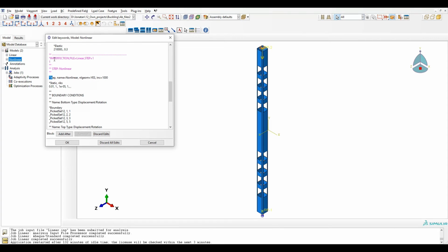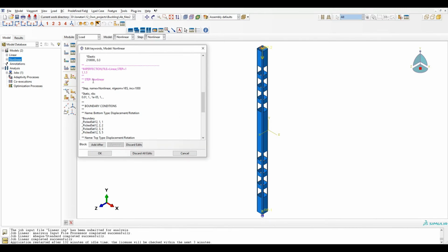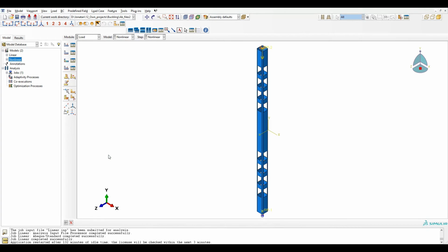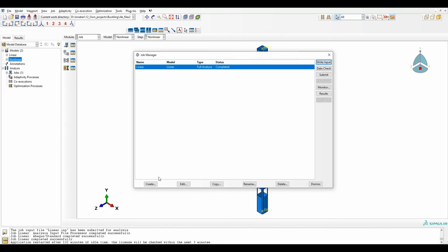So let's add the first mode, and here this value is 1/10 of, oh sorry, so the thickness is 20, so 2.0, 1/10 of the thickness, and okay, looks fine. So now the model is completed, so let's run it.